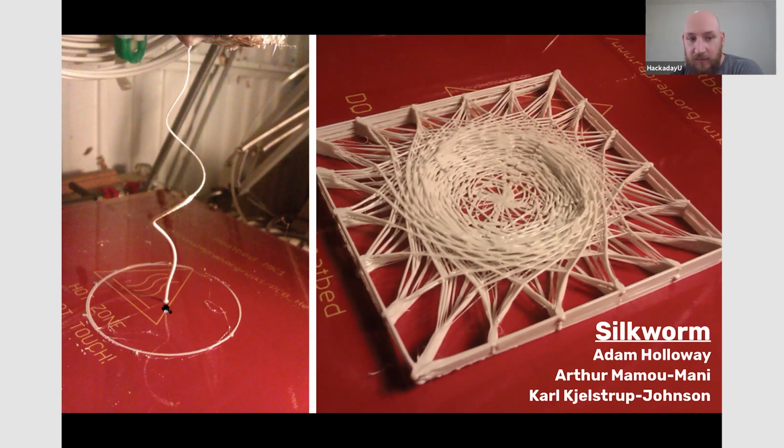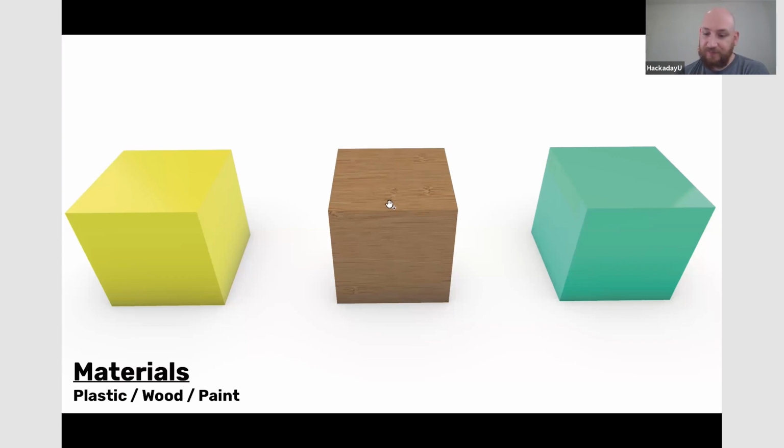and said that you can just move the 3D printer, turn the extruder on, and then move up vertically to create this kind of twirl piece. And in this side, to create that geometry, that's not going to work by horizontal layers. It's going to need to sort of move up and down and up and down and up and down to sort of create this weaving effect, which is quite an interesting hack on 3D printing.